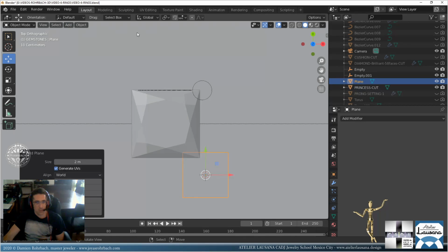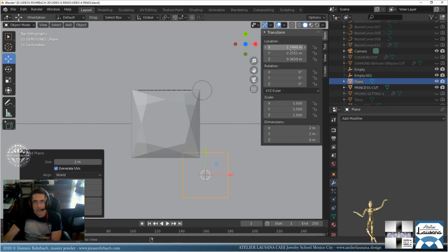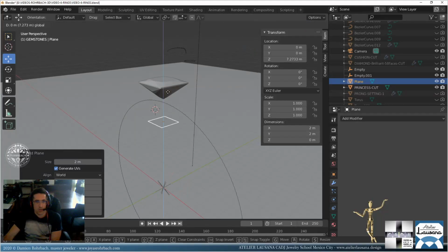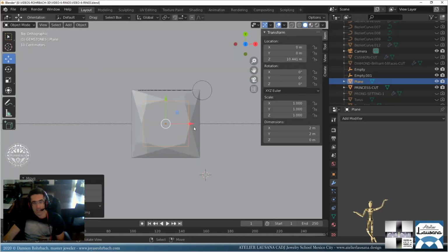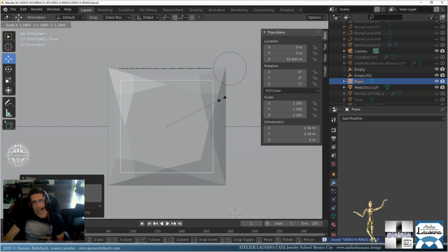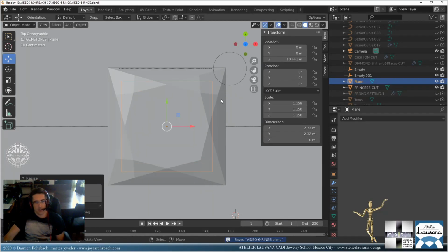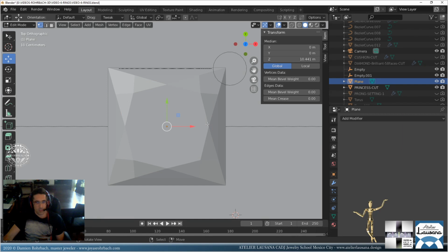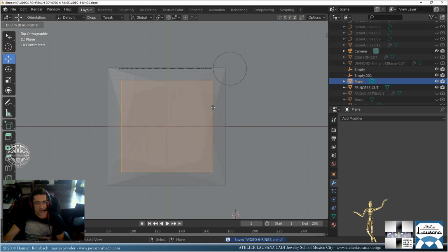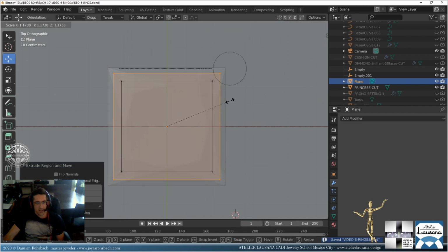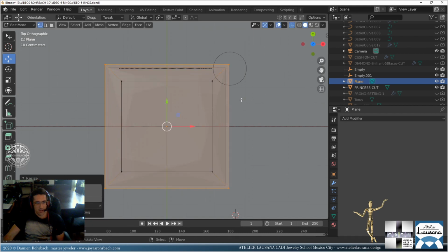Let's start by creating a plane. Let's center the plane somewhere here. Let's go up here, somewhere here. Yeah, perfect. Something like that. Okay, now let's go to edit mode. Alt Z to activate the transparency. And now let's make an extrusion. Click. Let's make this bigger here.